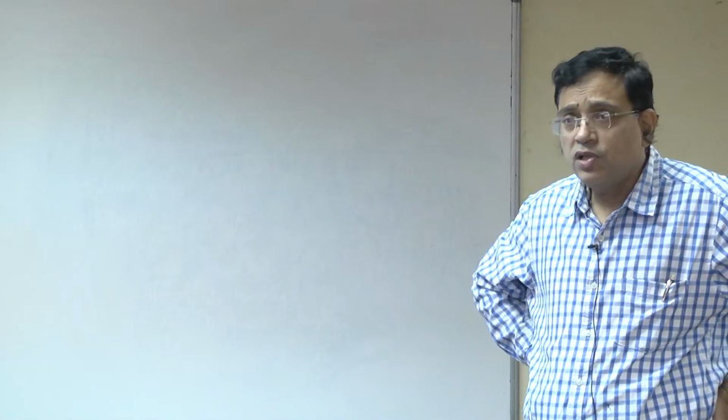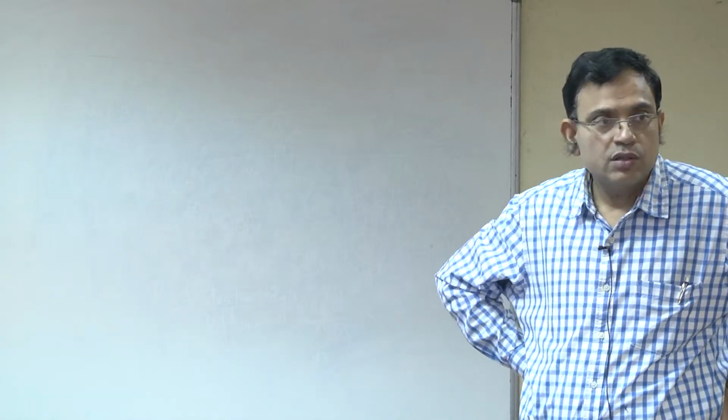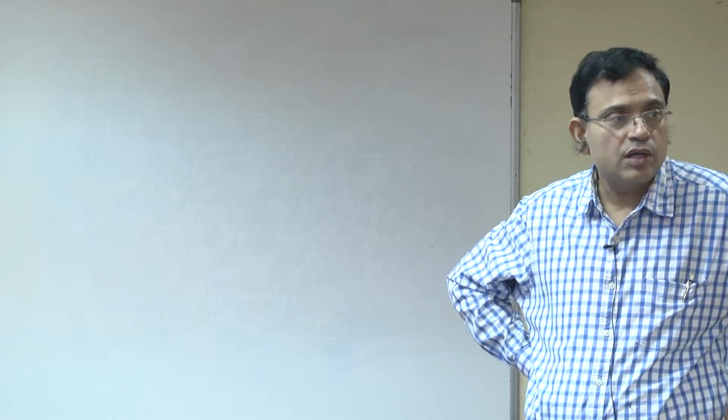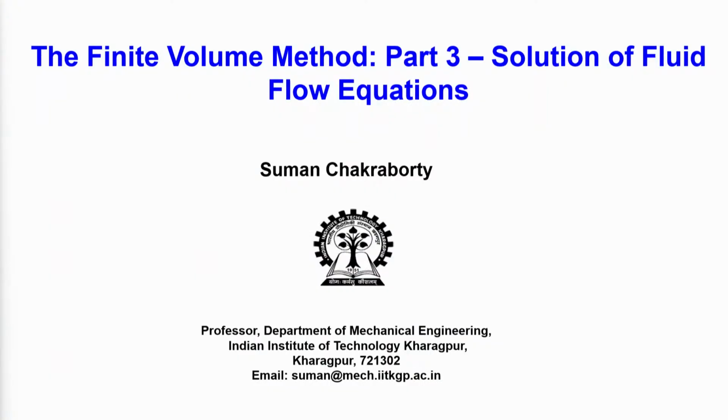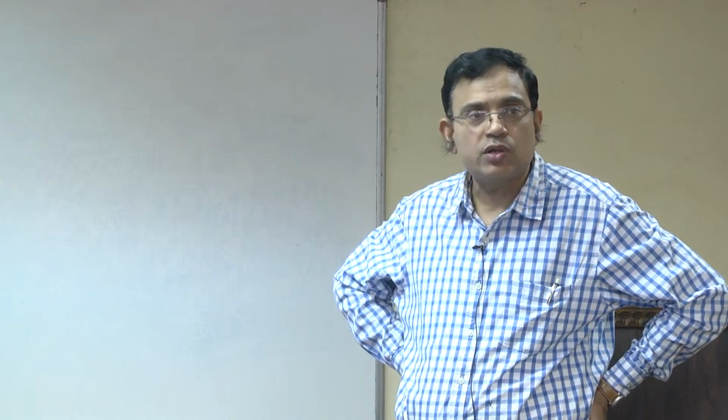The next one, our topic, which is perhaps the central thing that we look for in any CFD exercise that we are going to do, that is how we solve the fluid flow equations. So, we have solved diffusion type of problems, and many times fluid flow is also a diffusion type of problem. For example, if you have negligible acceleration or inertia is not present, it is like a diffusion problem.